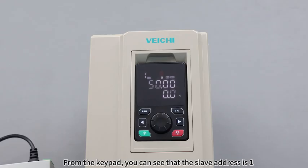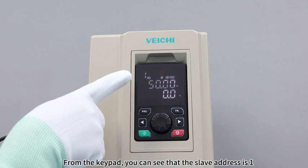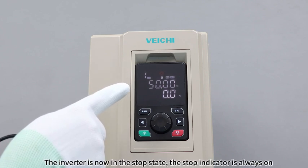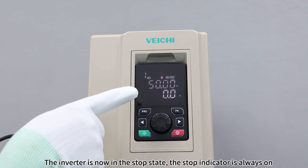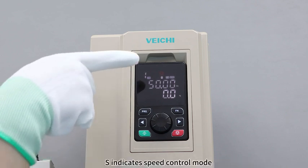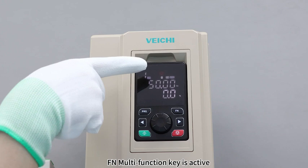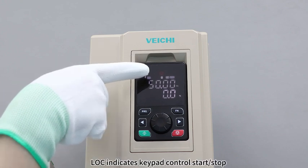From the keypad, you can see that the slave address is 1. AM indicates asynchronous motor control. The inverter is now in the stop state, the stop indicator is always on. S indicates speed control mode. FN multifunction key is active. LOC indicates keypad control start-stop.